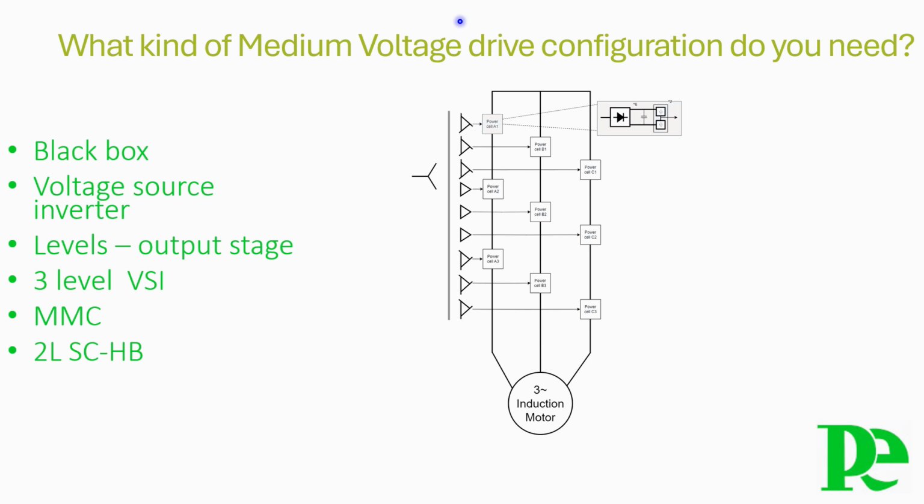less than 1% induced torque ripple, no need for an output filter for motor cable lengths even up to 2 km, a high reduction in common mode voltage, no derating on new or existing motor, no voltage spikes at the motor thanks to small output voltage steps, thereby indeed allowing the use or the reuse of a motor with standard insulation, ideal for retrofit. The integral dry multi-winding transformer